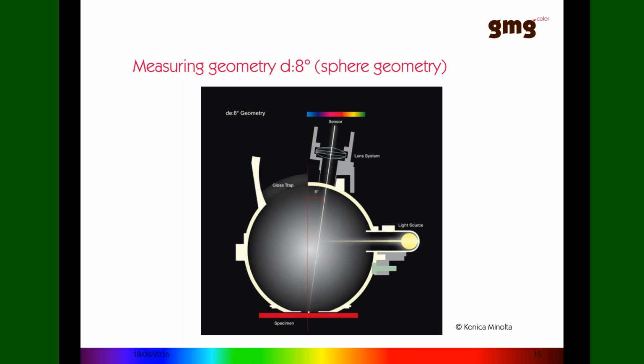Here we have an Ulbricht sphere, that's how this light bulb is called, which has a highly reflective coating around. So it's a nice body, and the light source is a bit outside, and it shines into this body, and the light gets reflected from everywhere, and then it shines from all the sides onto the specimen on the lower hand side that we want to measure.